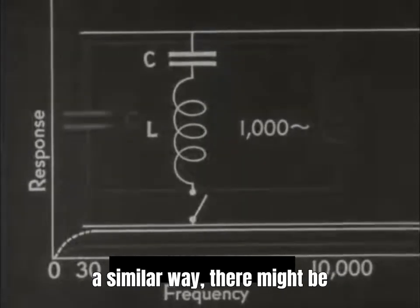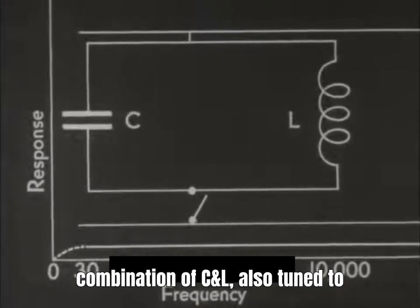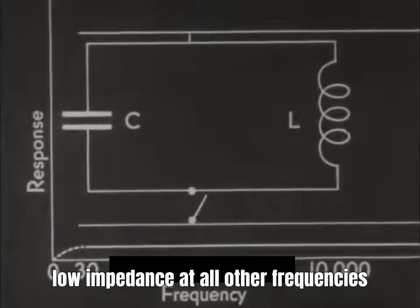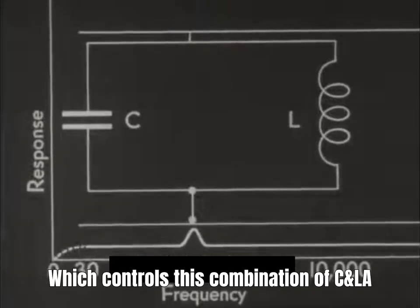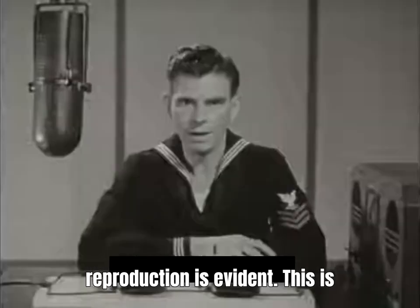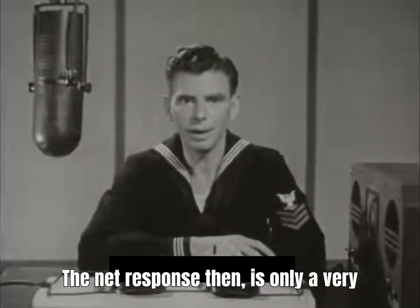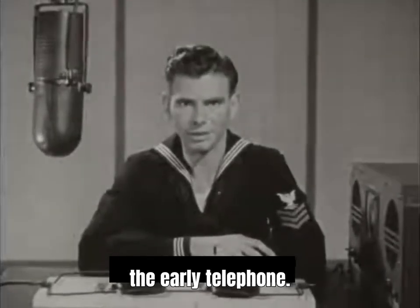In a similar way, there might be inserted across the circuit a parallel combination of C and L, also tuned to 1,000 cycles. This combination presents a high impedance near resonance and a low impedance at all other frequencies. When the switch is closed, which controls this combination of C and L, a totally different quality of voice reproduction is evident. This is because all frequencies except those in the vicinity of resonance are dissipated. The net response then is only a very narrow band of frequencies around 1,000 cycles, producing a quality not unlike the early telephone.